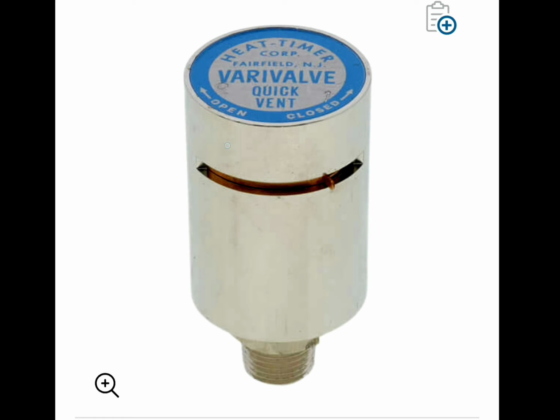And it's going to cool down most likely faster than this air vent, because the air vent is not hollow on the inside. Also, the thermostatic element on the inside is what helps to build up its matter of retaining its heat. And what I'm saying is you don't want an air vent that's going to retain its heat. You want an air vent that's going to quickly dissipate heat along with the radiator.